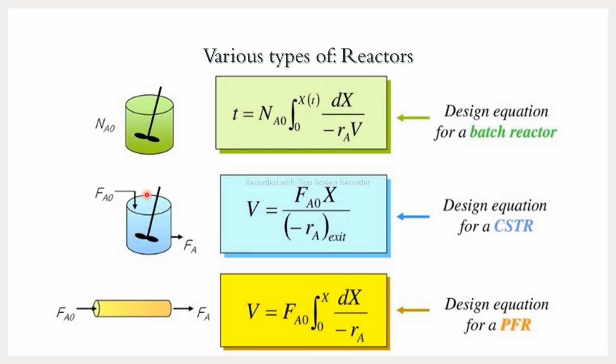If it sees that it is exceeding the optimum temperature, the control valve will be closed so that the amount of water flow gets decreased. It's a very simple example of how the temperature is maintained. There are also other cases where, let's say, a certain chemical is being dosed inside the reactor, so there may be a control system to control the amount of dosing also.